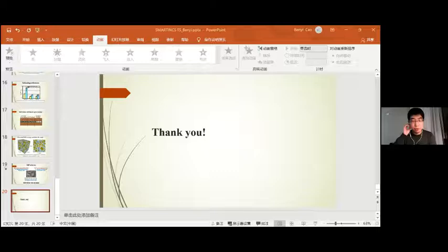Yeah, thank you. That's a very good question. The first thing is that the cement bentonite slurry is slightly different from the cement paste solution because we use less cement content. Therefore, the calcium concentration in cement bentonite slurry is lower than in cement paste solutions. And yes, the thing you were saying is right. The calcium ions can affect the microstructure of the SAP polymers. Therefore, some of this swelling capacity can be affected. But that's after many cycles.